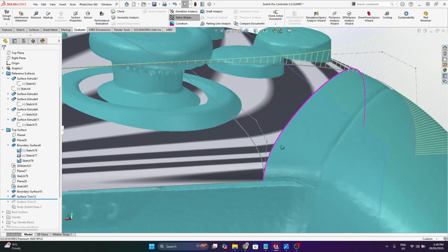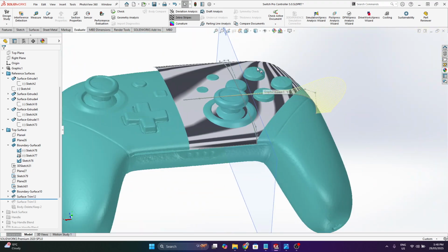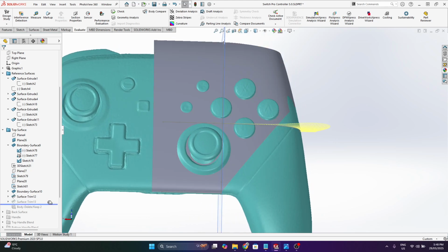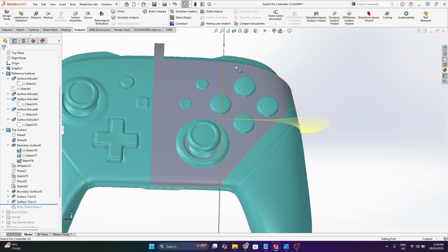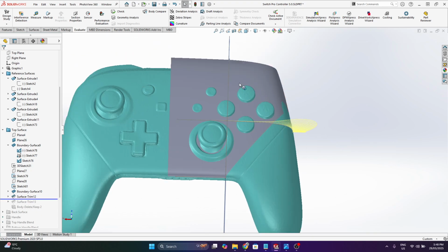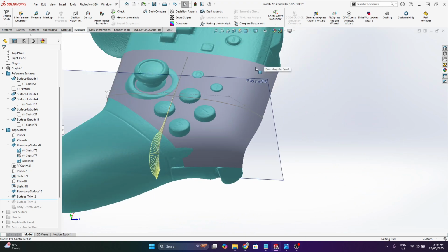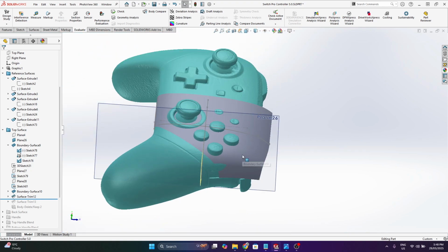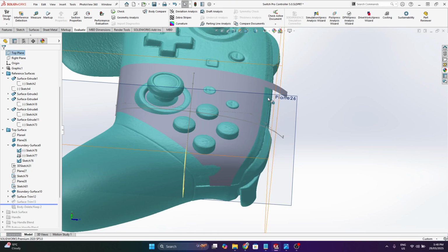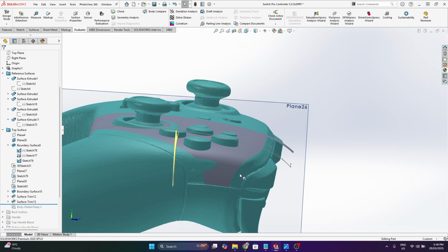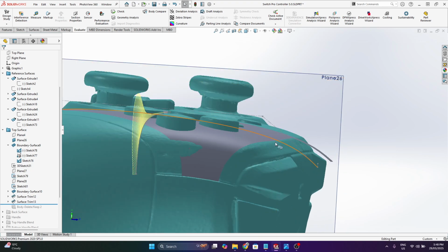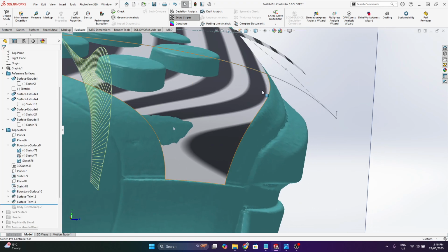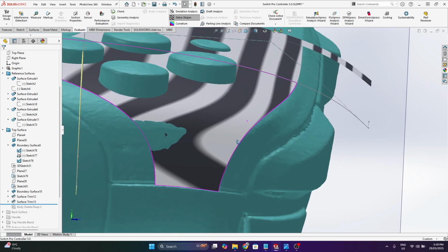But I can see here this allowed me to have a nice flow across these surfaces. And I did a similar thing up the top here. Had I tried to model this up to this boundary edge in one go, often what you get, because you're trying to follow a relatively complex 3D curve, is some buckling and warping, especially at the edges and the corners of these surfaces.